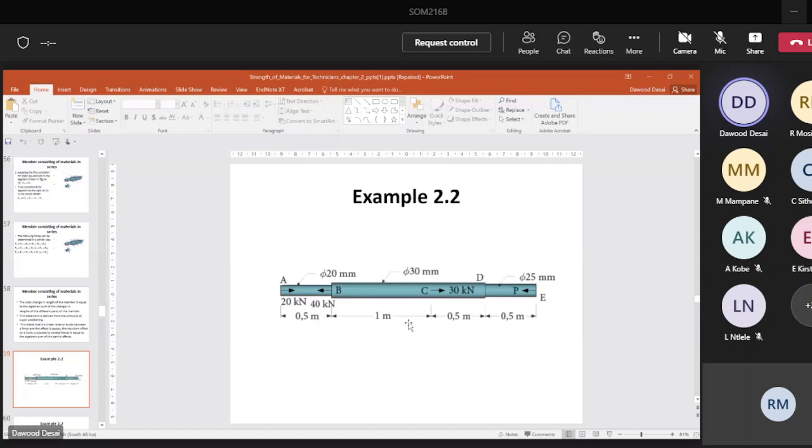So you put your hand at C. Any force through C vanishes. So the 30 goes. Now you got a tug of war. So you got minus, the 20 is pushing, and you got the plus 40 that is pulling. Remember, you consider summation of forces to the left-hand side of your hand, for the section you are interested in. So what is the answer? The answer is positive 20.